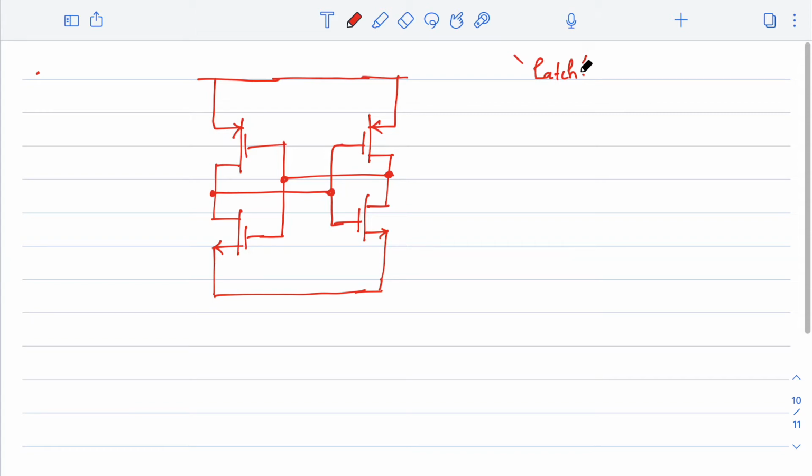All right. So what do you think? Will this work for the purpose we have discussed so far? Say I am just connecting this to VSS and this is connected to VDD. What I need here is, as mentioned before, we will not use any explicit capacitors. Rather, the voltages will be stored on the nodal capacitance, or the parasitic capacitance itself, right? So what do you think? How can I make this comparison happen?